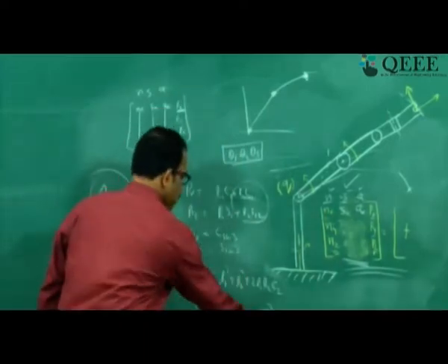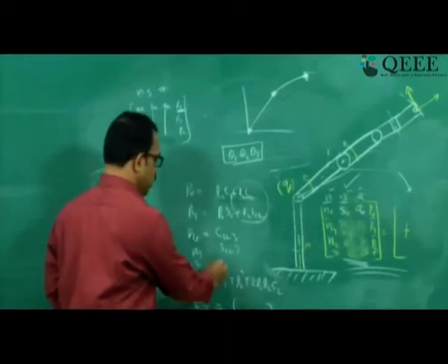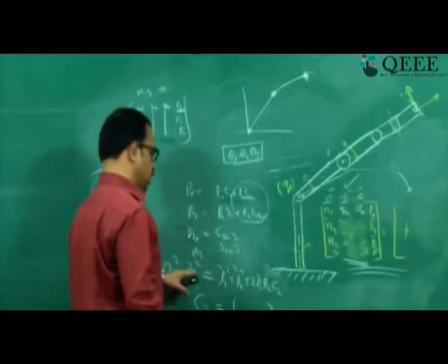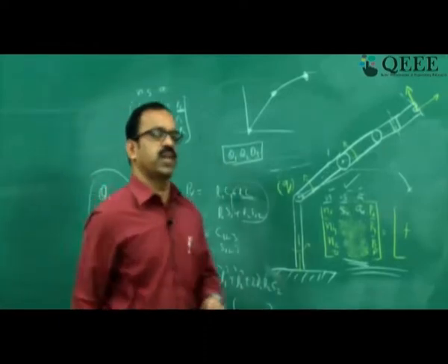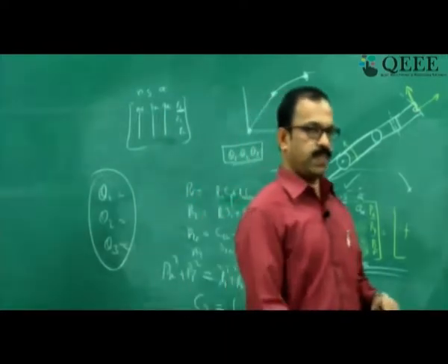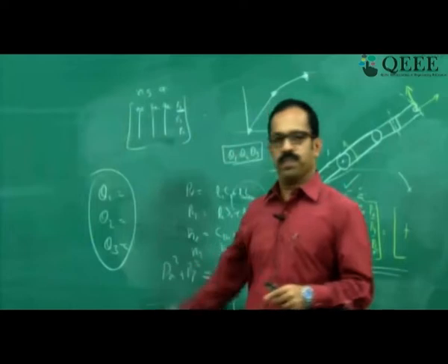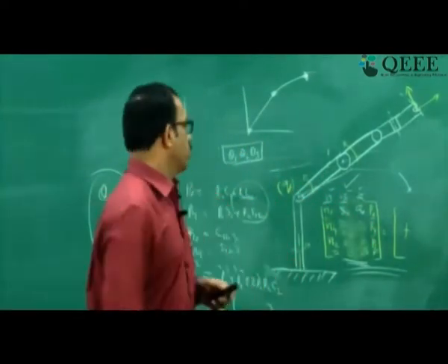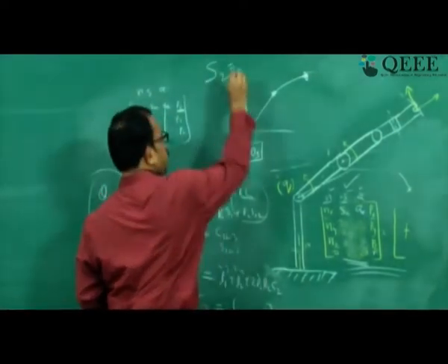So we have an expression for C2 with all the known parameters, because we know L1, we know L2, we know Px and Py, and therefore we can find out what is C2. So cos theta 2 can be obtained. Now we don't use this cos theta 2 directly to get theta 2, because that actually will lead to some other problem. So what we do, from C2 we will try to find out what is S2, sin theta 2.